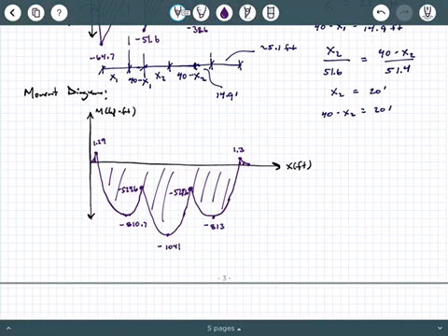We have a lot of negative bending in this particular example, which is very possible based on our column spacing and the magnitudes of our column loads. So from the moment diagram, you would use these values to calculate your flexural reinforcement. These are the Mu values you use to calculate the flexural reinforcement.